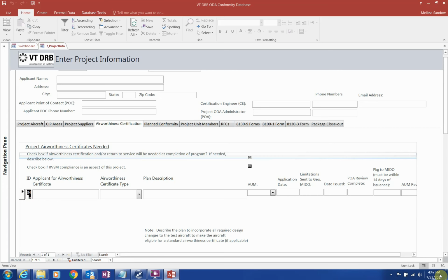When a company performs flight testing, they are conducting research and development to make sure their updates are safe and compliant. To do this, an experimental airworthiness certificate is used for R&D tests. When R&D testing is complete, an experimental airworthiness certificate to show compliance is issued so that the ODA, FAA, can conduct their testing. When concurrent flight testing is done, the company hasn't completed R&D testing, so that airworthiness certificate is not appropriate, and only the show compliance certificate will be needed.